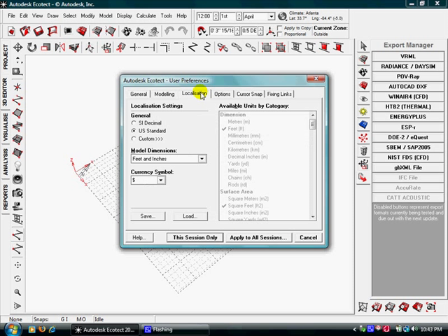Then in the localization tab, you have options for setting the unit system that you want for your project. You have the SI system, or basically the meter and millimeter type of system, and the US standard system, which is a foot-pound system. You can also customize it, and here also you can specify the dimension system that you want for your 3D modeling.